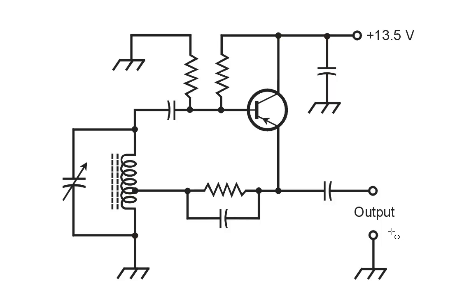Well, it looks like a perfectly good Hartley oscillator. There's nothing wrong insofar as choices A, B, or C are concerned. But if you're astute, you'll notice this right here. That is a positive voltage, a perfectly legitimate voltage, 13.5 volts. Perfectly legitimate value to be using with a PNP or rather with any bipolar transistor in a Hartley oscillator.